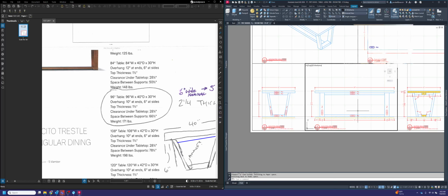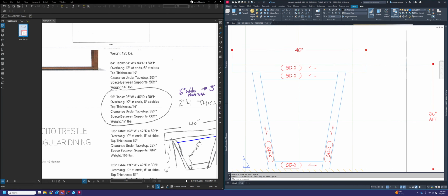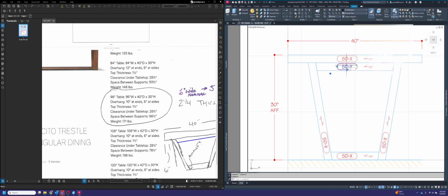Little fun thing you can do too, because this is open in the middle and over here as well. We can make an open to beyond call or callout. How to do that is I'm going to copy a material call, go down to the drop down on that material call, go down to text with 2 arrows, and then we're going to write in here open to beyond.